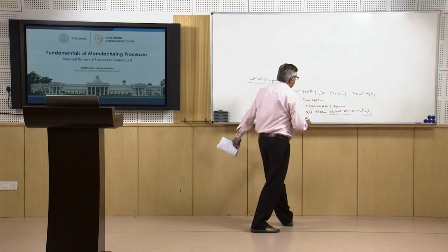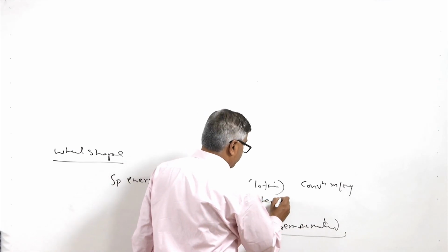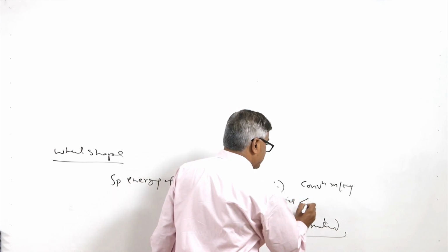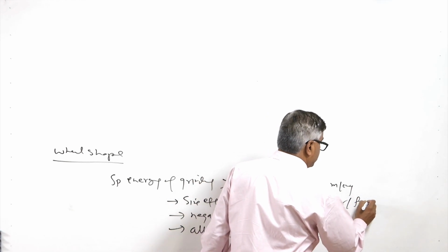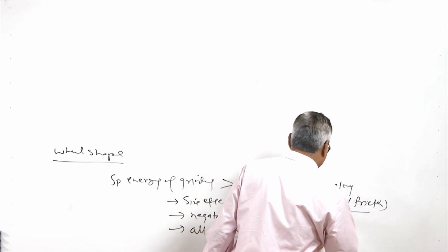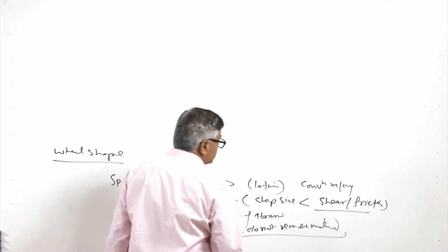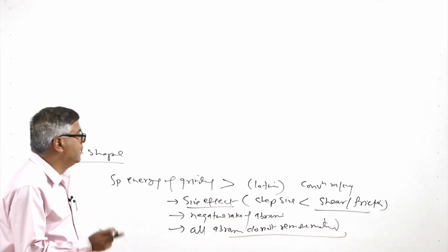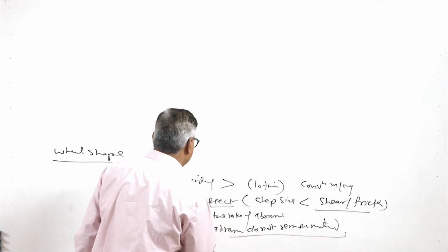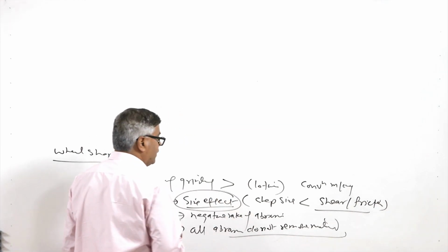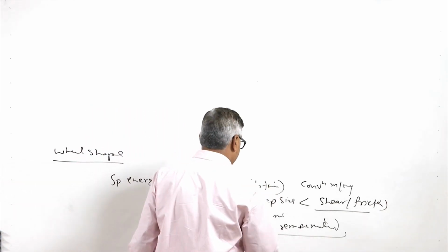So, in any case when the chip size is less, the size effect increases the shearing and the energy required for overcoming the friction in general for a given volume of the material. Since the chip size is very fine in case of grinding as compared to that of conventional machining, that is why it leads to much higher energy consumption per unit volume as compared to that of the conventional milling.